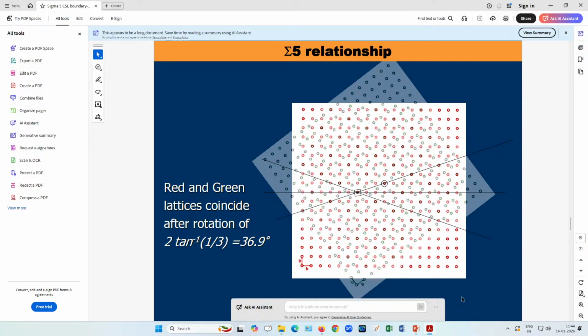Once you rotate one crystal with respect to another along the z axis, which is 001 typically, you can see that there is a certain periodicity you can find out here. Consider either the blue lattice or the red lattice, and see the periodicity. Can anybody figure out what the periodicity is? Periodicity means out of how many atoms both atoms are coincident. Coincident means superimposing one above another.